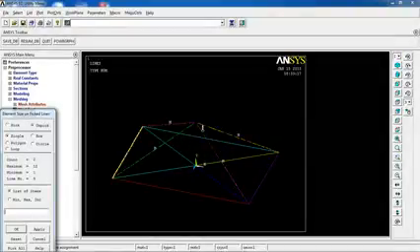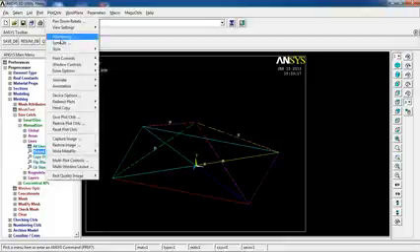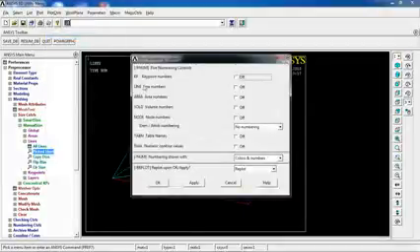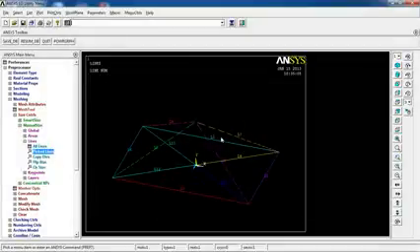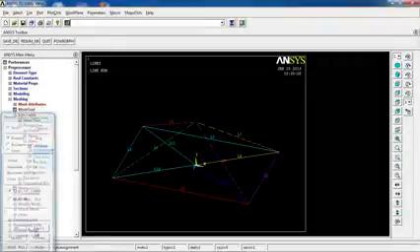Okay. Because it's getting a little bit hard to pick that line, what I want to do is to come to plot controls, numbering, have line numbers on. Okay, so that one is L or line 1. So I'm going to pick line 1, apply,